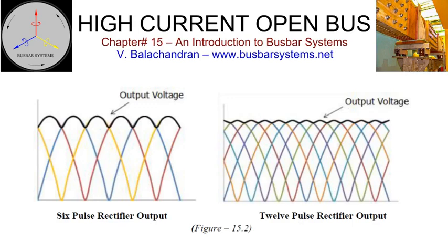The dominant harmonics for a 12-pulse rectifier are the 11th and 13th harmonics. It can be theoretically established that the predominant harmonics will be twice the number of phases plus or minus 1. 24 and 36 pulse rectifiers are also in use with associated phase shifting transformers in some plants. Diodes and thyristors have been used for rectification, and both these technologies compete in the market.